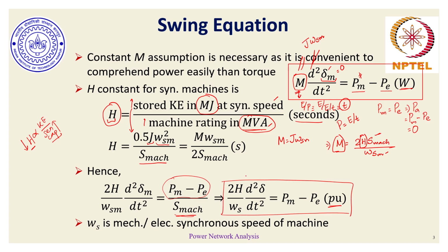The answer to that lies in this particular question: let's say we have a unique disturbance which is happening in two scenarios for a power network. In one scenario, the power network doesn't have many renewable energy resources connected to it, specifically solar PV and battery energy storage systems, which tend to reduce the overall H. That is one scenario. And in the other scenario, our power network has high penetration of solar PV and battery energy storage systems, in which the effective value of H tends to go down.